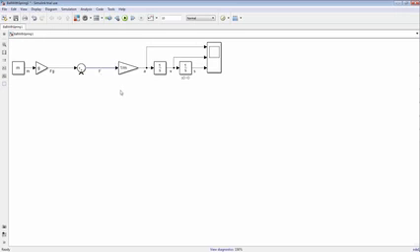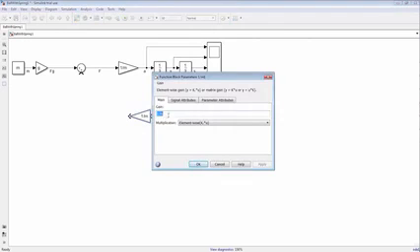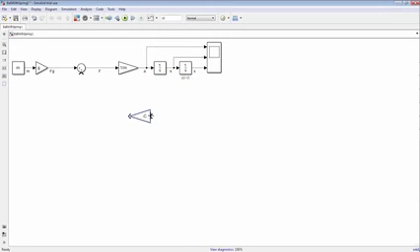And now I need the spring constant. You just copy it using Ctrl+C and Ctrl+V. This is not the orientation I would like, so in the context menu you've got the flip block. This looks better. I need multiplication by minus c. So you refer to the constant c and use it as minus c. Minus c times s is the new force that I have to supply here, to be added. And of course you have to add the constant c that we are referring to in the Model Explorer. Right now it would be 0.